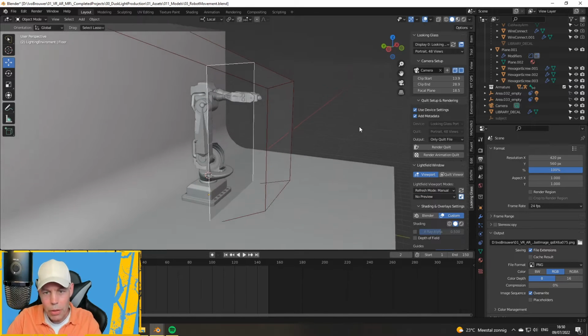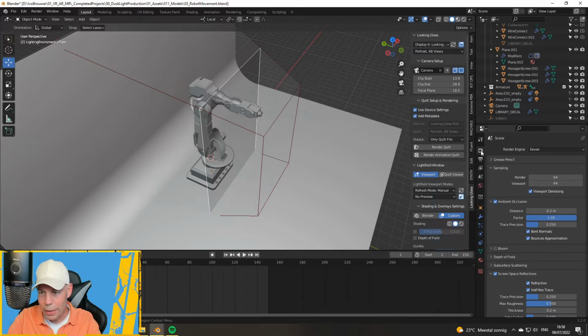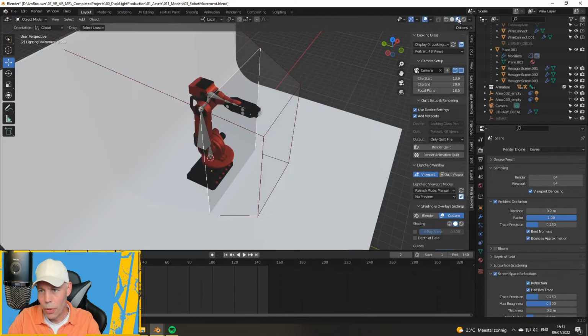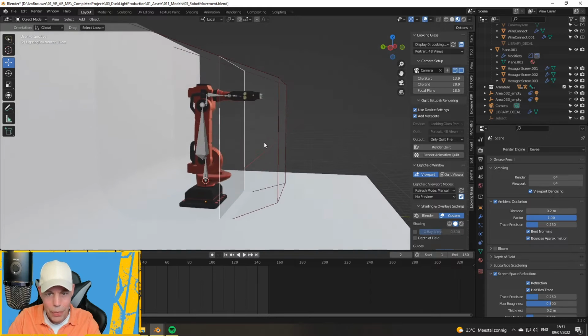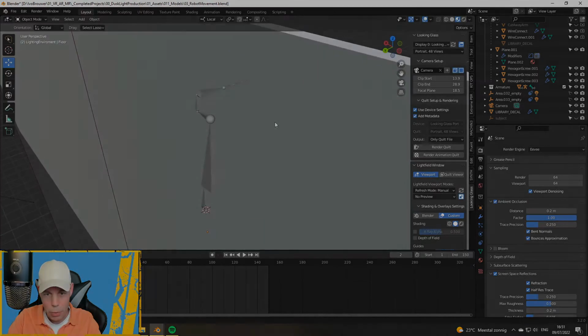It's a gray image, which we may not like. We would like the colors. To do that, go to the top tab in Render, it says Render Properties. Make sure your render engine is at Eevee, not at Cycles, but at Eevee. Then go to the top and change to Viewport Shading, and bam, there you are. Everything is in color. If you click now on the refresh mode and have your low resolution preview or the other ones turned on, you'll see your fully colored model on your display.